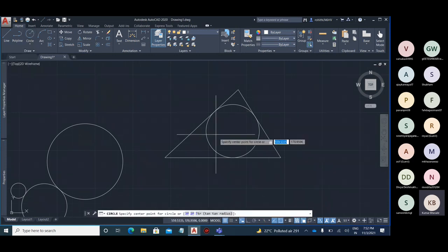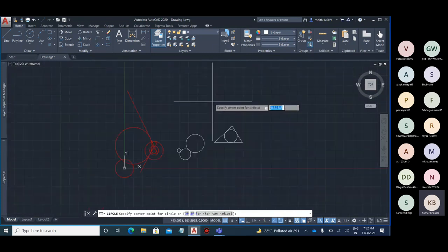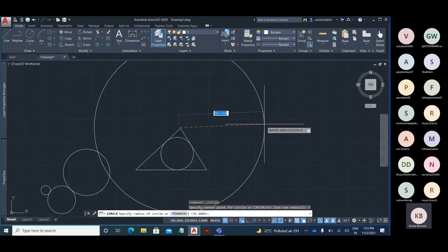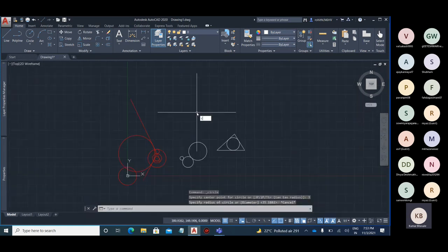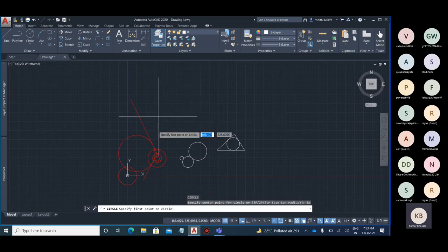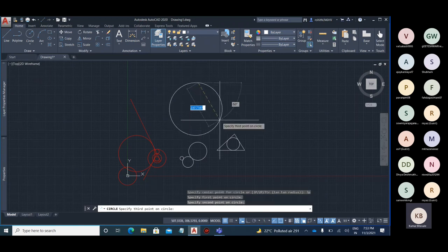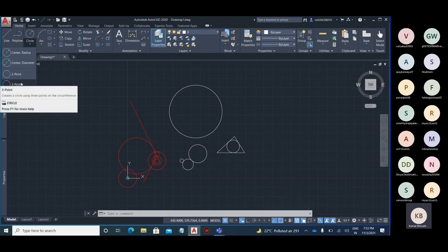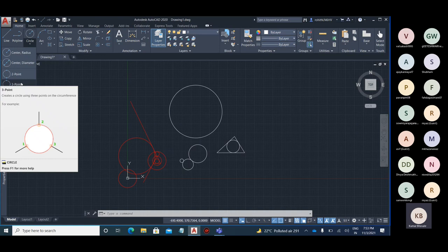Now of course you get some options at the start only. So when I'm in the circle command, you can see 3-point, 2-point, tan radius options. From this only, say I want 3 points, so give 3, give space. Just a minute. Circle, yeah. Now give 3P and give space. Now you can see 3-point circle starts. So whatever is shown in blue, you have to type that completely, and then only you can use the shortcut instead of every time going over here and changing the settings of what type of circle you want. I hope this is clear to everyone.